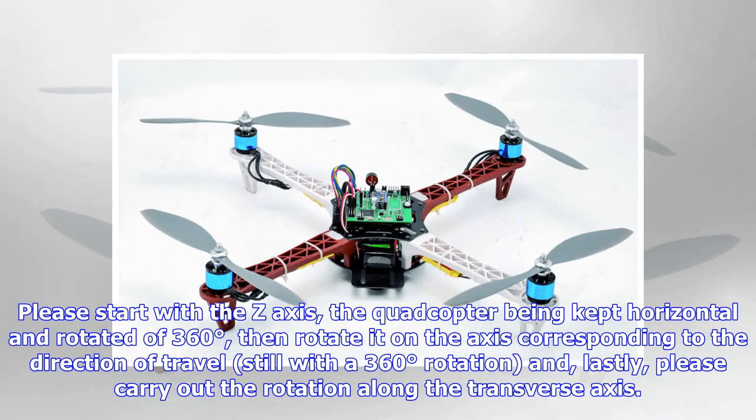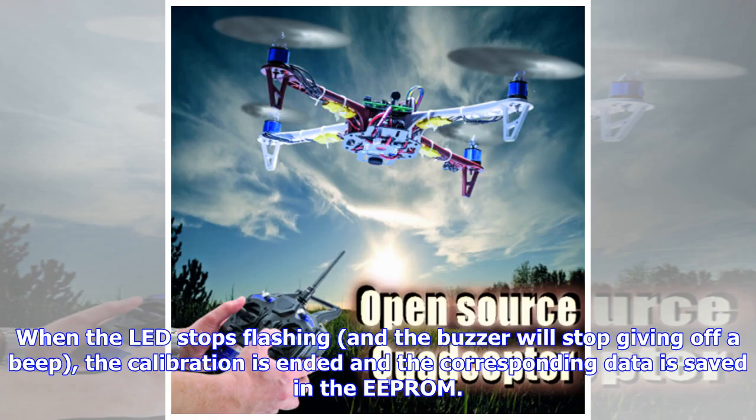Please start with the Z-axis, the quadcopter being kept horizontal and rotated 360 degrees, then rotated on the axis corresponding to the direction of travel, still with a 360 degrees rotation, and, lastly, please carry out the rotation along the transverse axis. When the LED stops flashing, and the buzzer stops giving off a beep, the calibration is ended and the corresponding data is saved in the EEPROM.